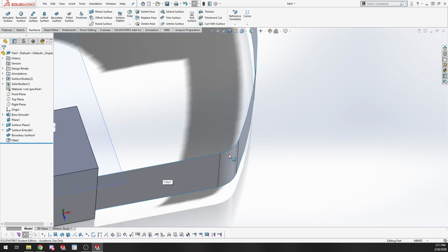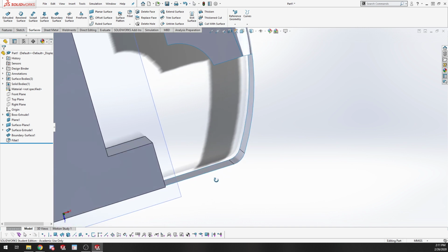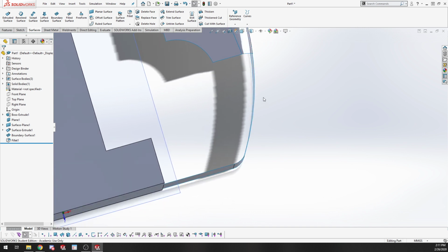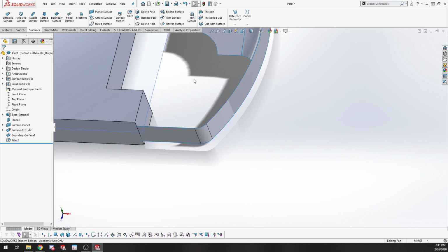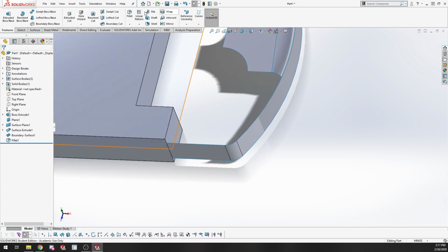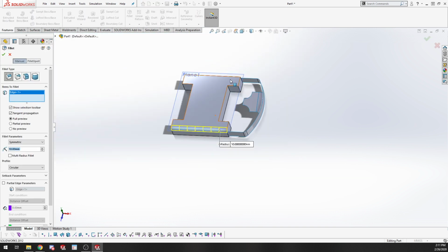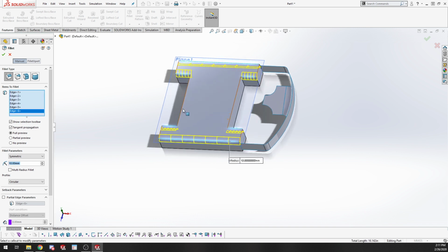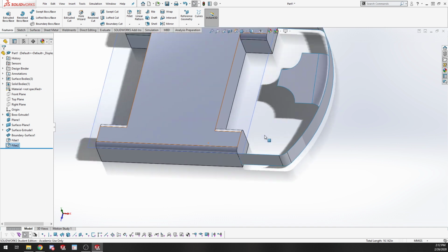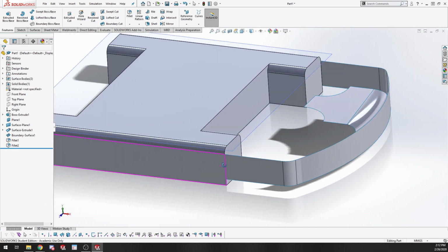What it does is within that surface, smooths it out. And again, we're creating zero thickness geometry. So just push that in. Then I can go, I kind of want to make probably another planar surface that goes between these two. Actually, what I want to do, should have done this initially, but I want to actually fillet. Where is it at? There it is, right in front of me. I want to fillet these edges as well here. We're going to be working with them later on. Yeah, 5 millimeters. Cool. So there we go.